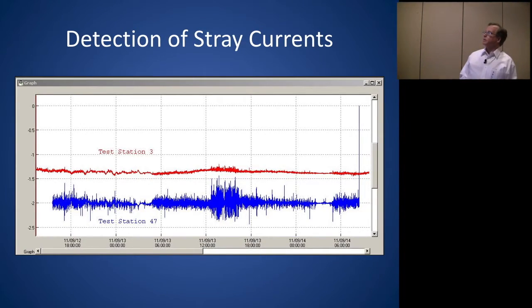If you have a pipeline and you're measuring the voltage on your pipeline, this is what it's going to look like. You saw on the transit system, the rail voltage is a lot. It's like plus minus 50 volts, sometimes 70 or 80 volts. On a pipeline, you see we're talking plus to minus a couple of volts here. So that's kind of a relationship between what the voltage is driving the stray current and how much stray current can get on an alternate conductor.